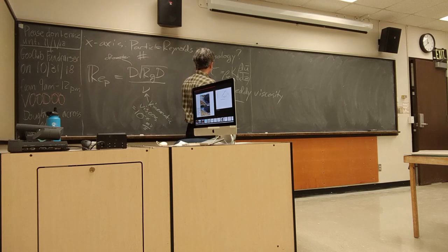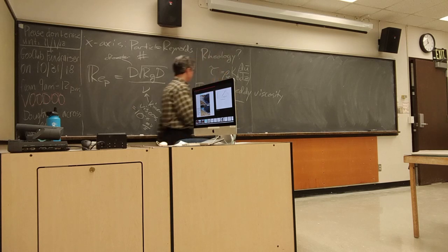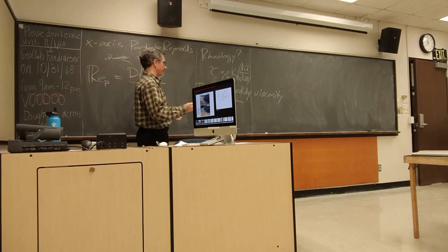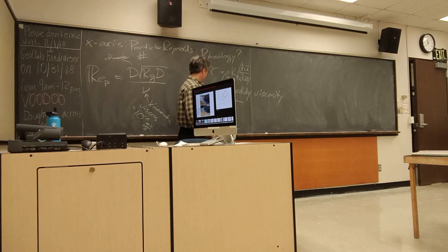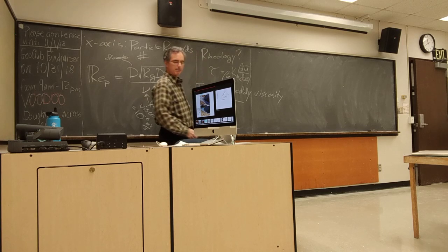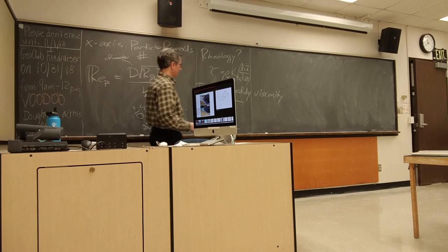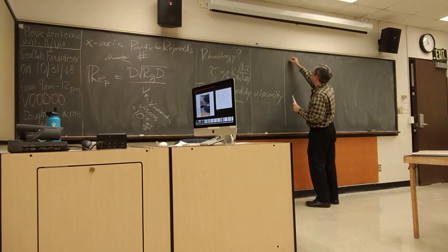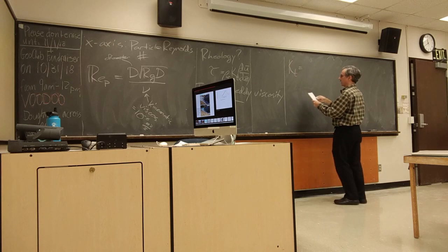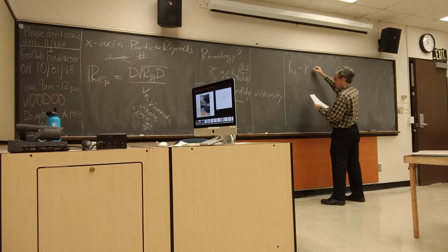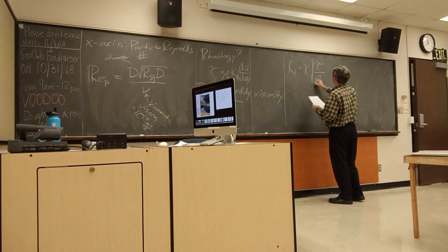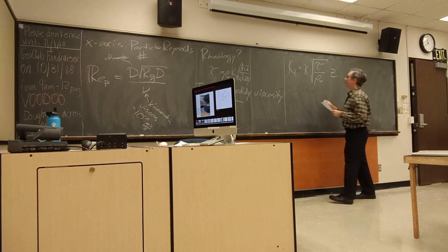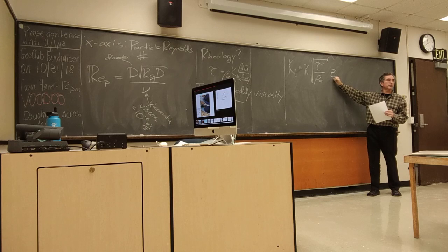So that's one thing. This turbulent eddy viscosity is a bit of a funny character because, as I've drawn here, it's going to depend on the sizes of these eddies. It's going to be smaller near the bed, larger farther from the bed. So I'm just going to write something. I'm going to say that my turbulent eddy viscosity increases with height above the bed.